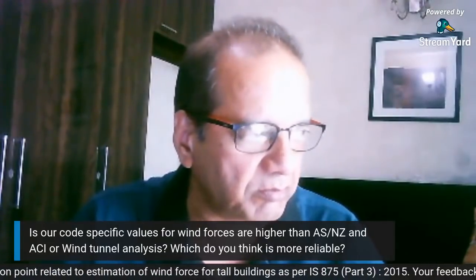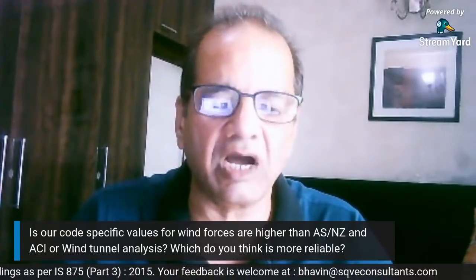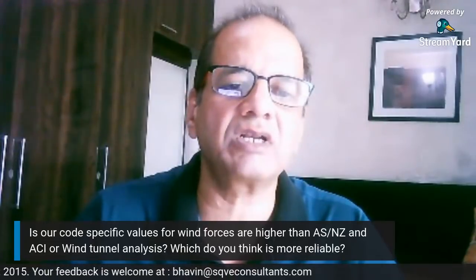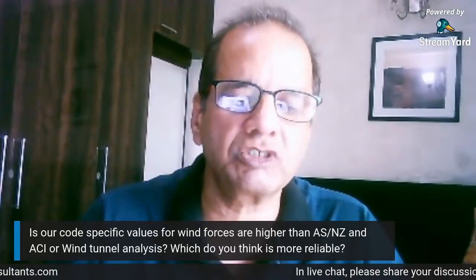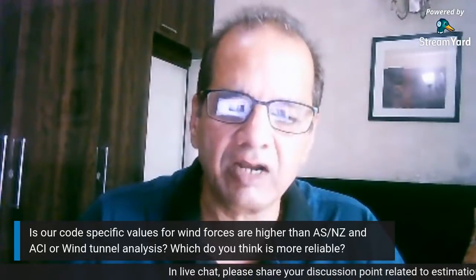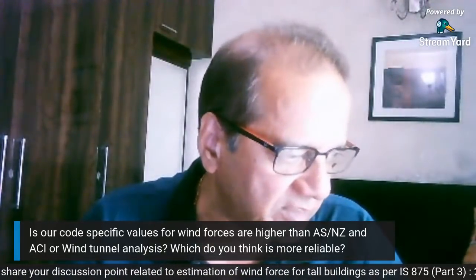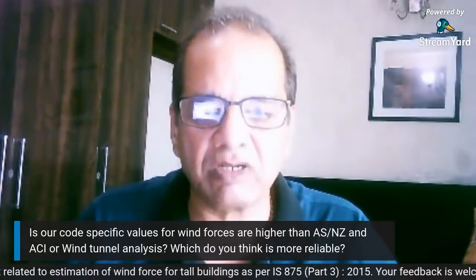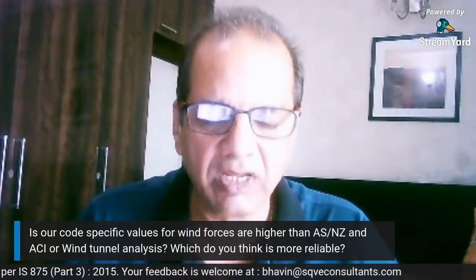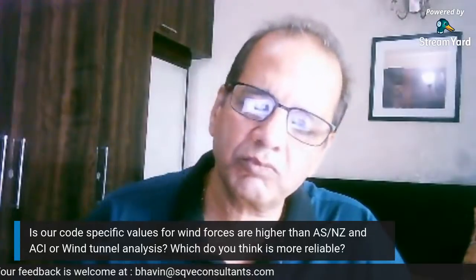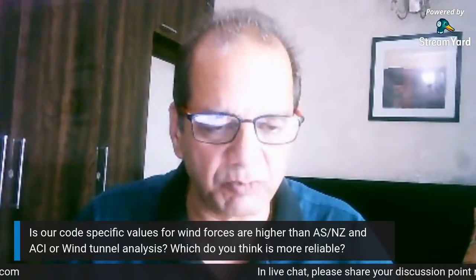The user can refer to an exercise done in 2006 in India, the harmonization of the international codes on wind engineering. That workshop was done in 2006 in India, and those proceedings must be available somewhere on the internet. There, 3 problems were identified: one low-rise, one mid-rise, one high-rise, and these 3 building problems were solved using some 8 different country codes, and the results were compared. So basically, all are similar depending on the averaging period which has been used.